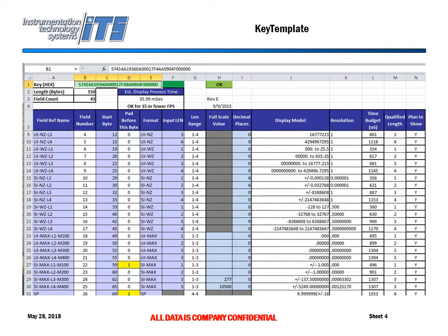And our equipment generally supports 2 KLV packets, so you can actually define with 2 of these keys 70 bytes of data that's collected in synchronism with the video sampled on each video vertical sync equivalent.